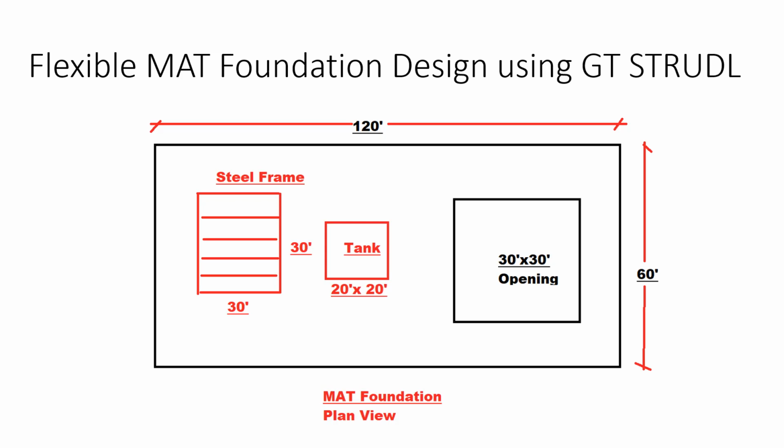In some cases, we need to go in and round things off, and most preferably, we would like to have a nice square rectangular arrangement of the mesh. But if it becomes impossible, then we would use other types of elements such as triangular elements.